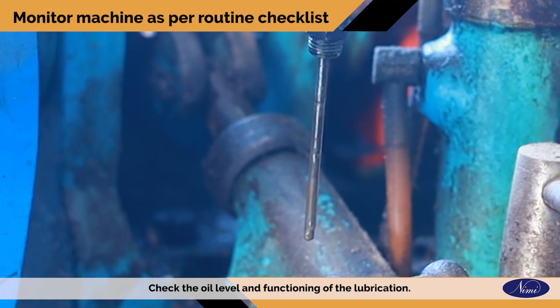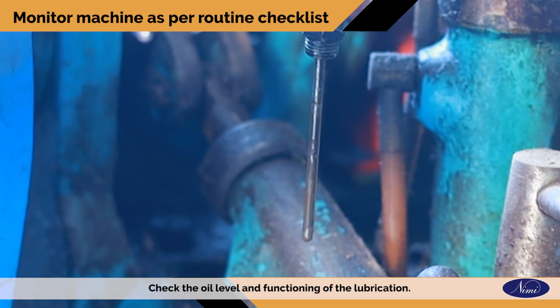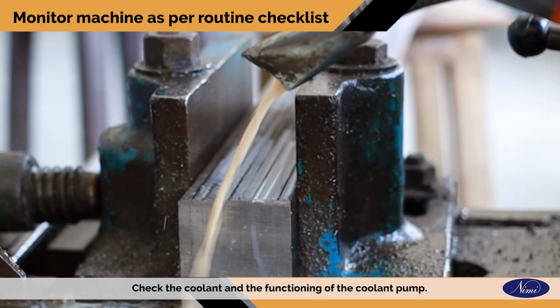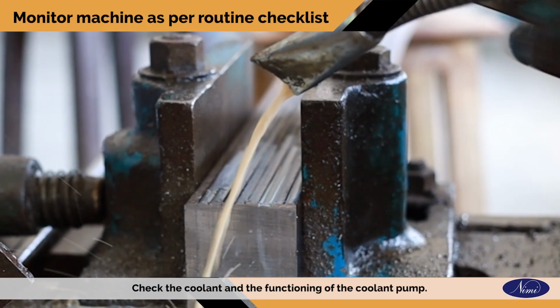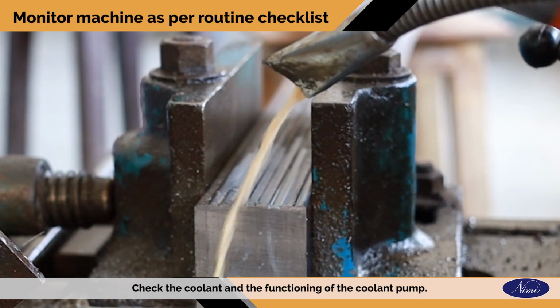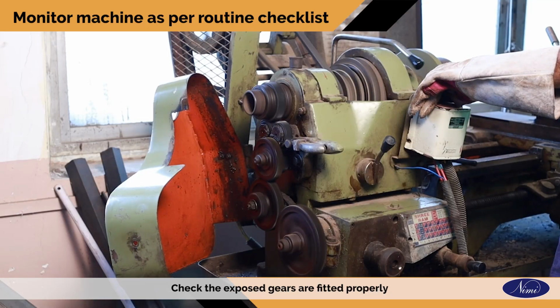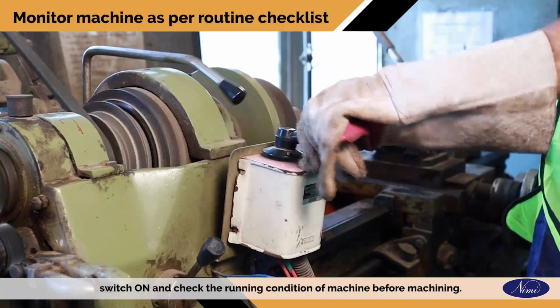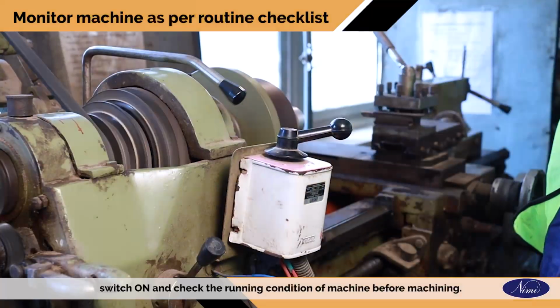Check the oil level and functioning of the lubrication. Check the coolant and the functioning of the coolant pump. Check the exposed gears are fitted properly. Switch on and check the running condition of machine before machining.